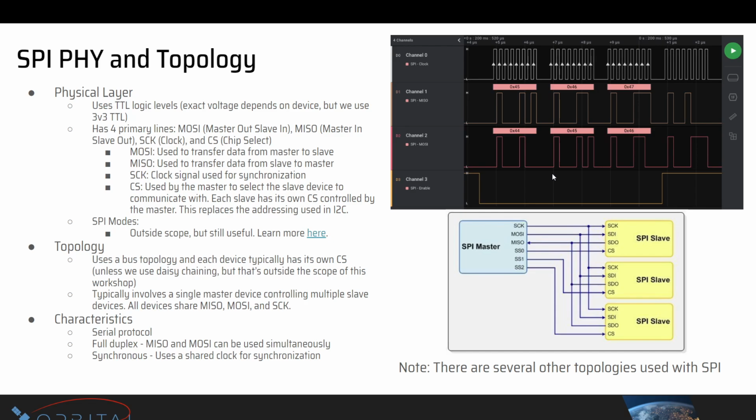If you're using an oscilloscope, you can also see how clean the signal is. Like I mentioned with I2C, if your pull-up resistor has a bad value, you could get signals that aren't clean, which causes issues because they can't be interpreted properly. Maybe it's not even reaching 3.3 volts. It only rises to 2.4 volts before it gets pulled down again, so you never reach a one. You could debug it by probing that test point with an oscilloscope to see what the value is.